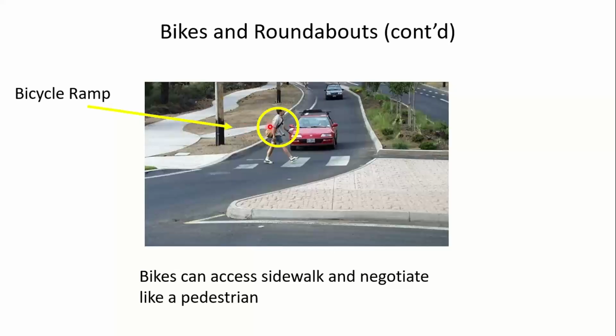So we wouldn't want to put a detectable warning surface here because we really don't want pedestrians entering the street here. So the issue is, how do you make this connection usable by bicyclists, but also discourage the visually impaired? And this is where those directional indicators I mentioned earlier may have some applicability here as well. And we'll talk about those next week. Can't remember whether it's Tuesday or Thursday, but we'll talk about those. That's another potential location for the directional indicators.